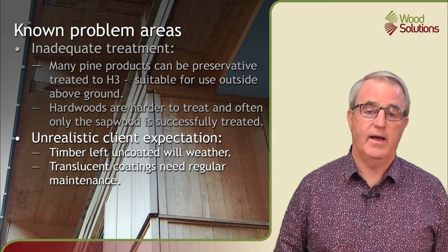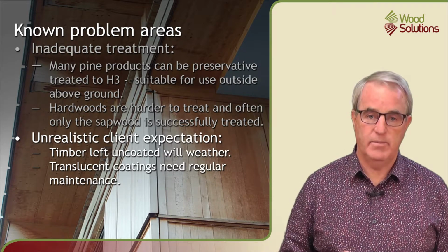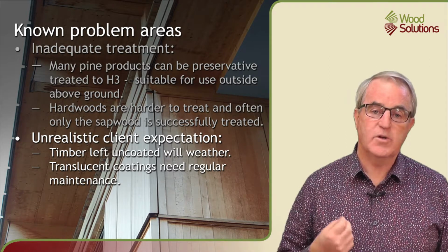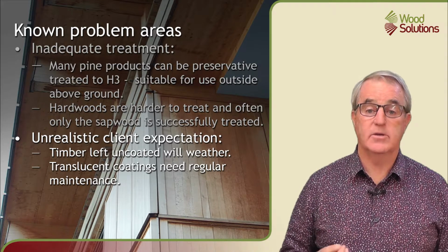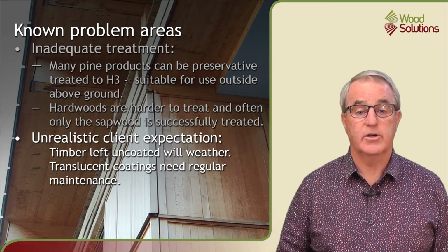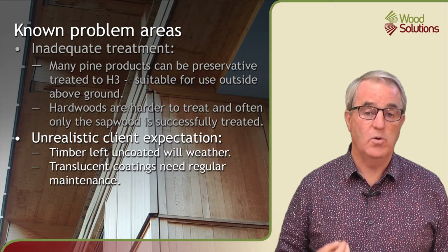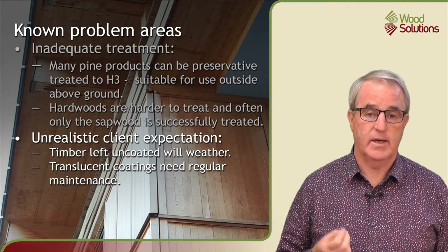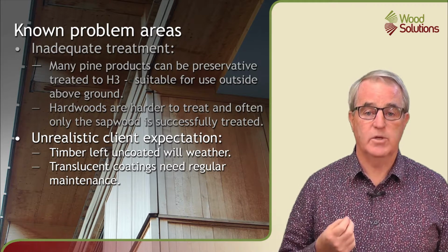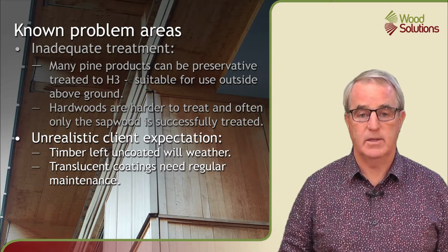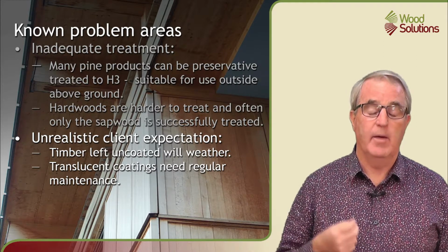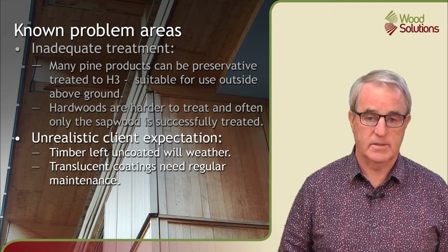Next, clients can have an unrealistic expectation of how the timber product will perform and how it will look over time. First, all unpainted timber products used outside will weather. That means they will first discolour and they will eventually turn grey. Treated material also weathers. The treatment doesn't protect and stop weathering. The rate and evenness of weathering depends on the wood species and the patterns of exposure in the building. Translucent coatings can slow or delay weathering, but the coatings need regular maintenance.